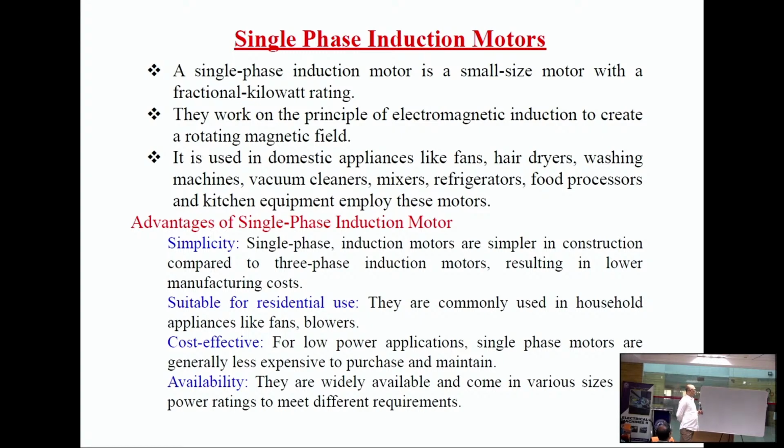So the single phase induction motor is a small size motor, generally of fractional kilowatt rating, and it works on the principle of electromagnetic induction to create a rotating magnetic field. We will see how the rotating magnetic field is produced.